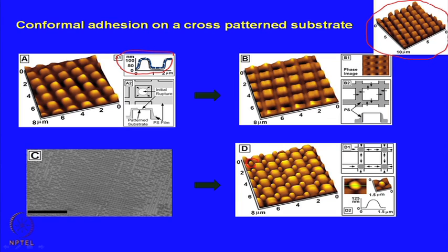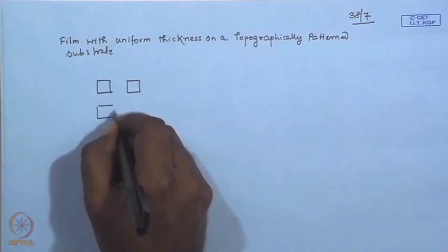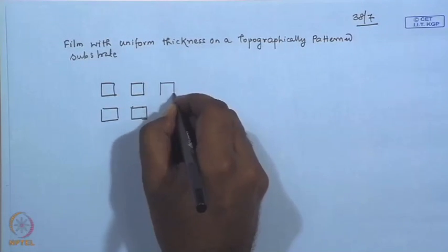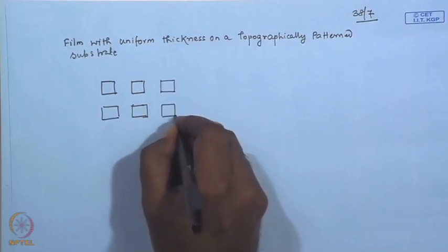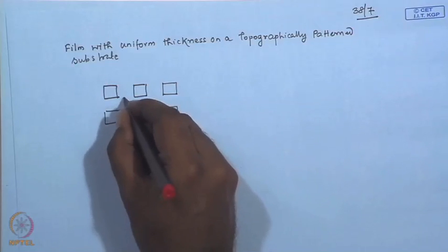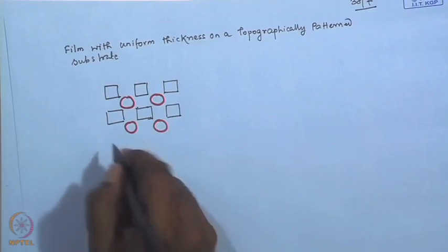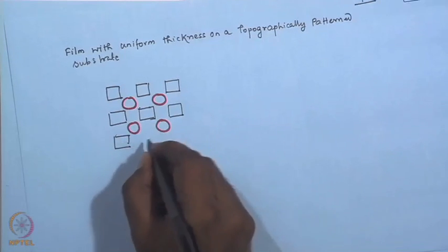You see, this is the original template, and by dewetting of this film, what has happened is that at each of the interstitial locations between the channels... So, here was the structure. This is an array of square pillars onto which you have floated your film and then allowed it to dewet. So, what you see is that every interstitial location gets filled up with one dewetted droplet.